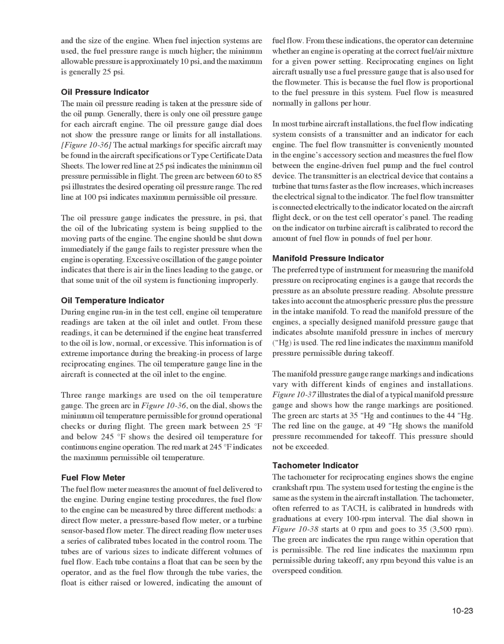Fuel flow meter. The fuel flow meter measures the amount of fuel delivered to the engine. During engine testing procedures, the fuel flow to the engine can be measured by three different methods: a direct flow meter, a pressure-based flow meter, or a turbine sensor-based flow meter.